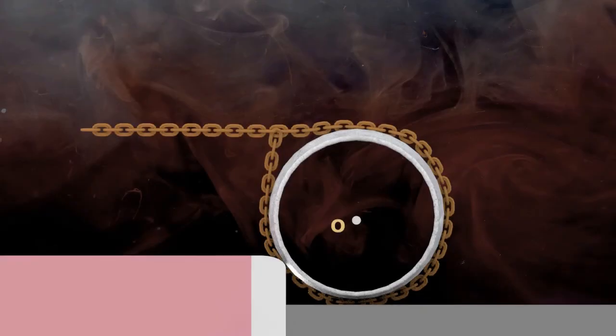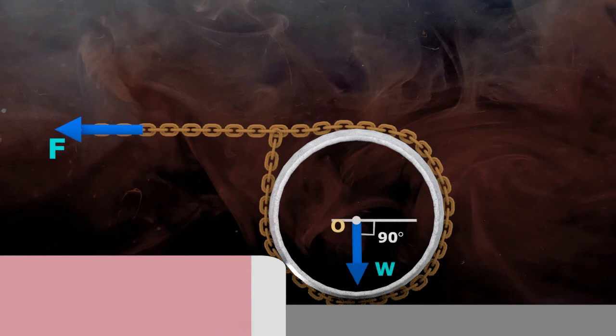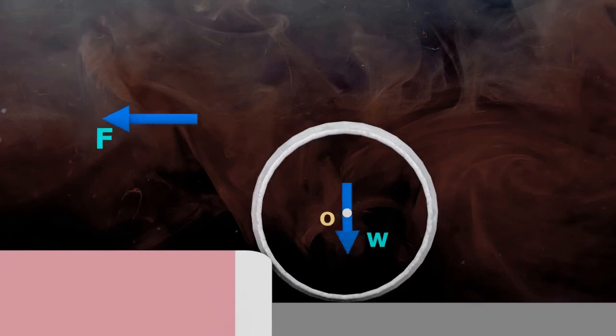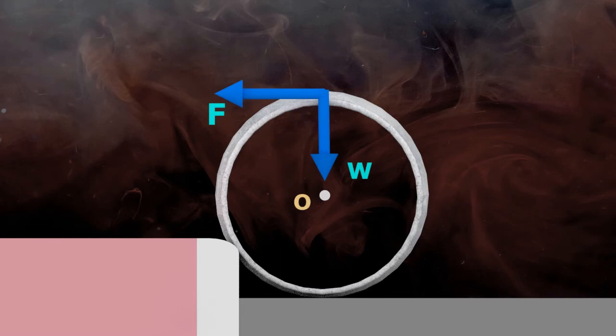Again, consider the side view of the pipe. Let's find out all the forces acting on the pipe and their direction of application for this case. External force F is acting in horizontal direction, making 0 degree angle to the x-axis. Self weight is W, which is acting in vertically downward direction through the center of gravity O, making 90 degree angle to the x-axis. Now, if the lines of action of weight W and force F are extended, they meet at point C.